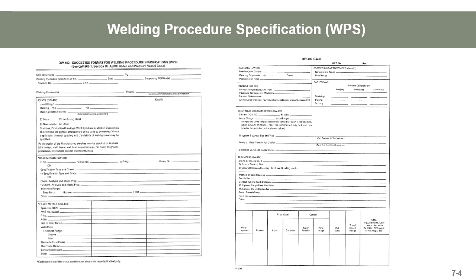Gas tungsten arc welding does. So you have gas, not as with shielded metal arc. If you're writing a shielded metal arc welding procedure, don't address shielding gas. So that's the advice, or the rant, for the welding procedure specification.